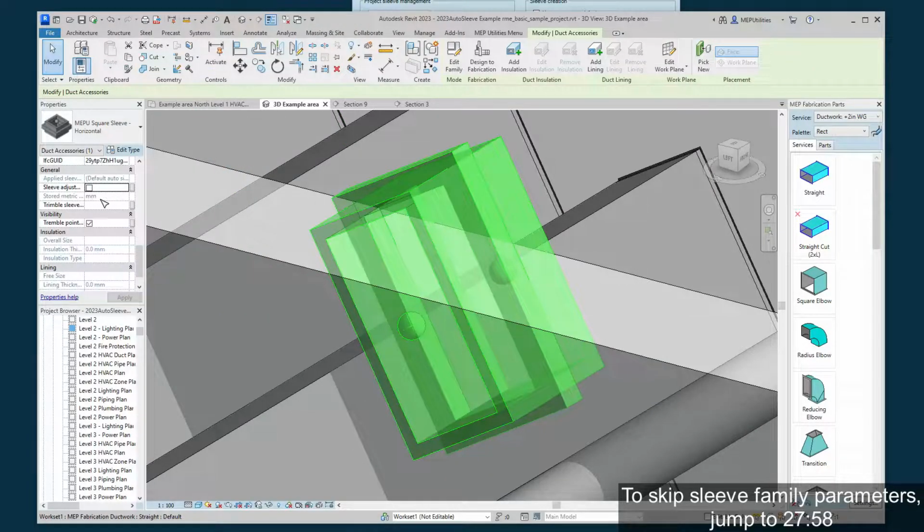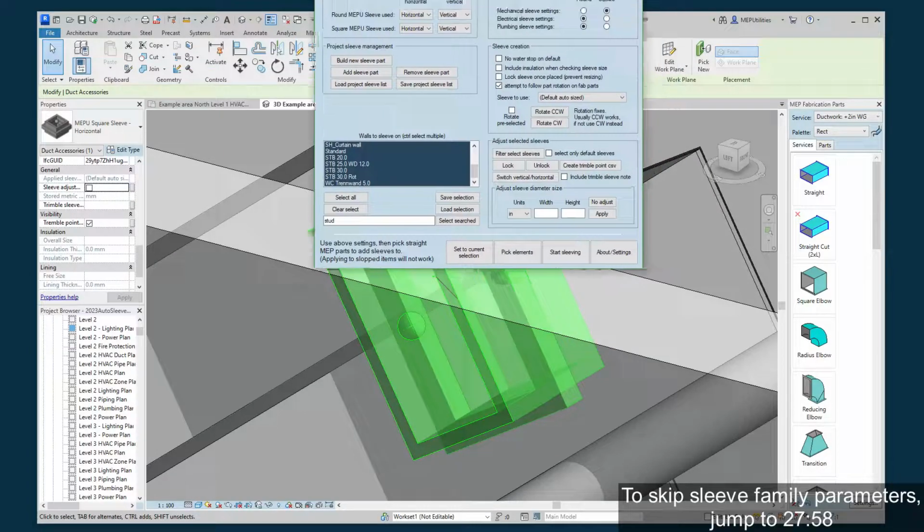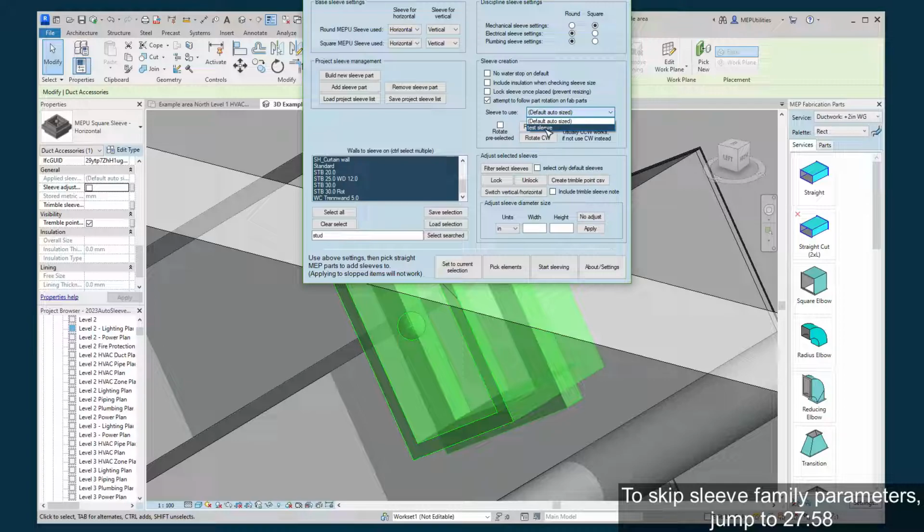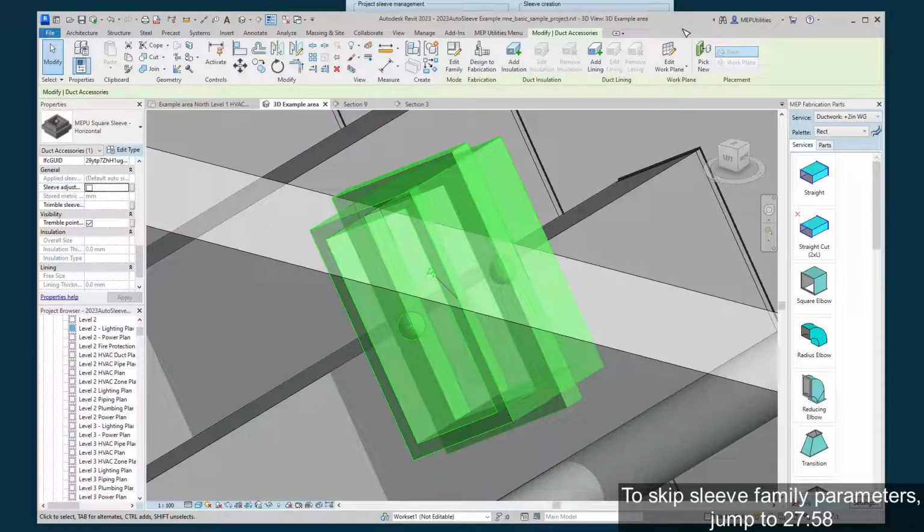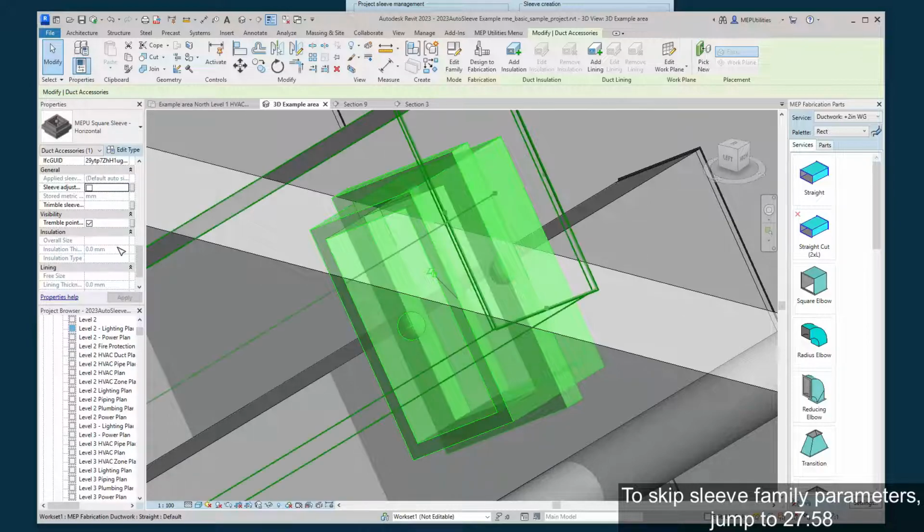And the stored metric that was used, so millimeters, that's not important in this particular sleeve. It'll be more important for the pre-built sleeves that you have added, because those will have actual sizing on them. This is just automatically sized to fit the duct and stuff, so it doesn't really make sense for the millimeters to matter. But when you have a pre-sized sleeve, it will have the information numerically on it for what size it is, and you can make use of that information as you need.